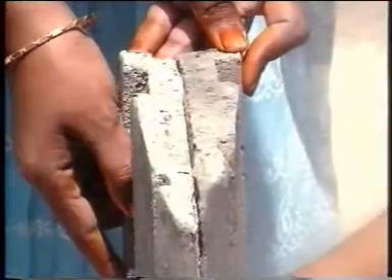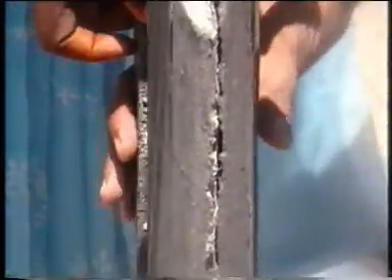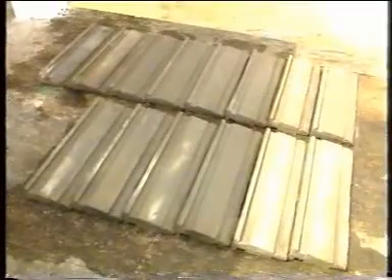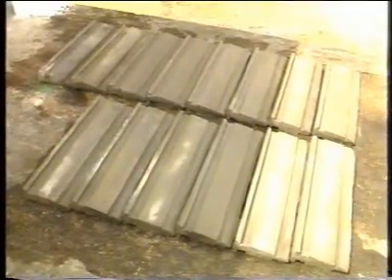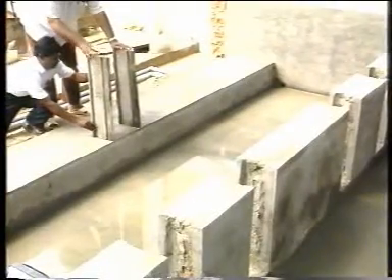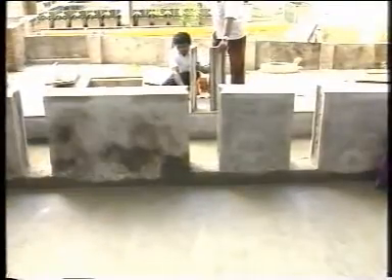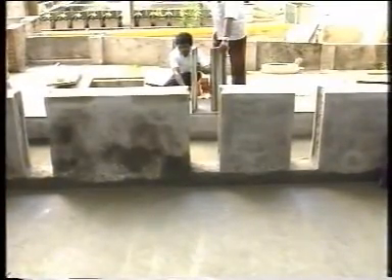As the construction work of the walls of the model progressed, preparation of molds and casting of trash rack piers and slabs is made. Once the model reaches the bed level, precise location of trash rack piers is determined.